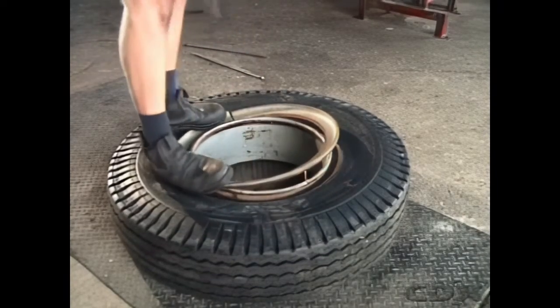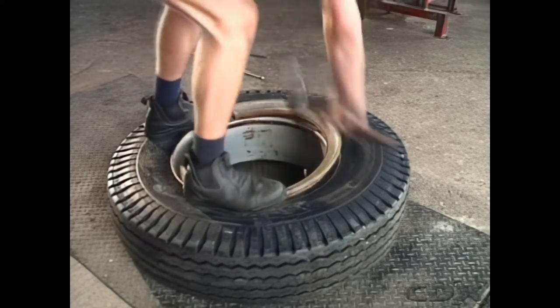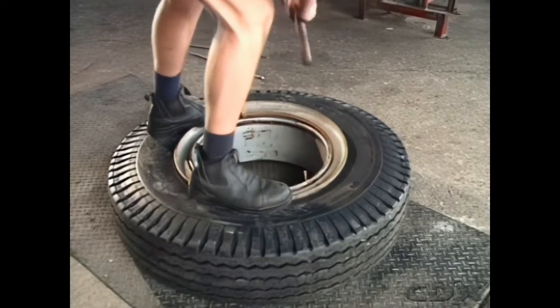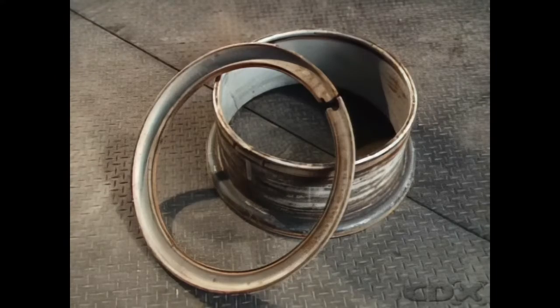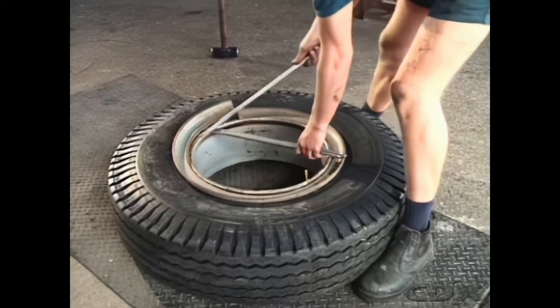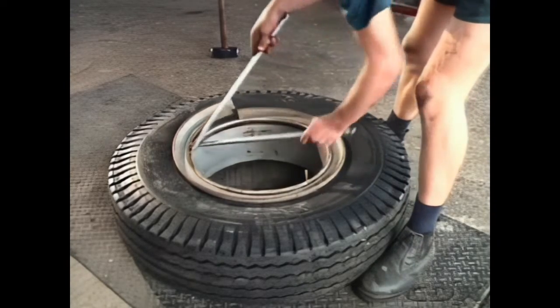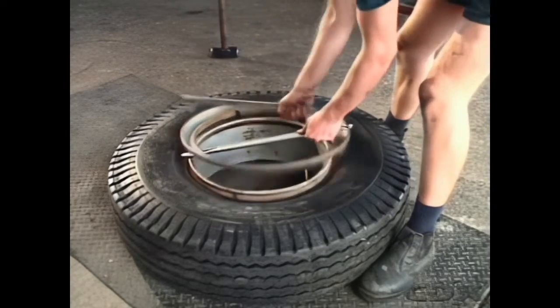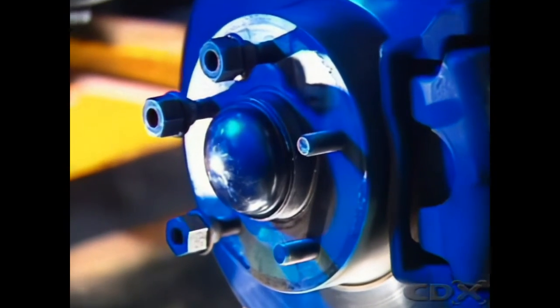The stiff sidewalls of larger cross-ply tyres mean they cannot be mounted and demounted in this way, and many four-wheel drive and commercial vehicles use a flat-base, demountable flange rim. When all of the air is removed from the tyre, one flange can be removed so the tyre can be demounted. Wheels are fastened to the hubs by wheel studs and nuts.